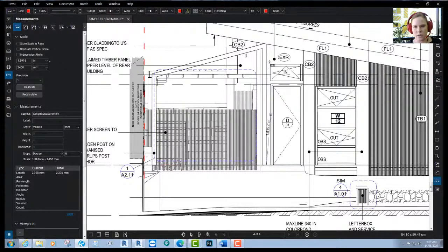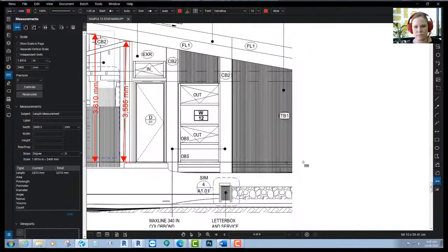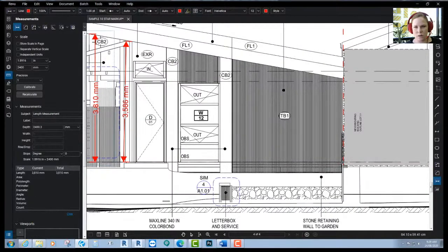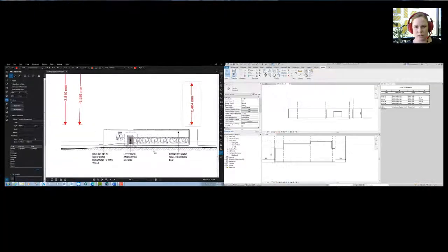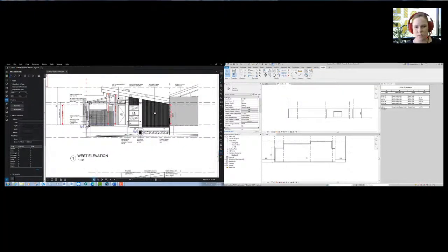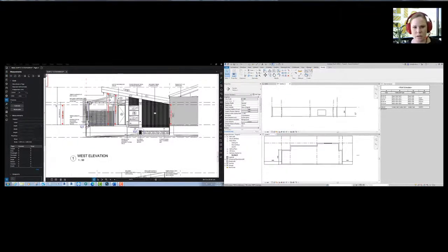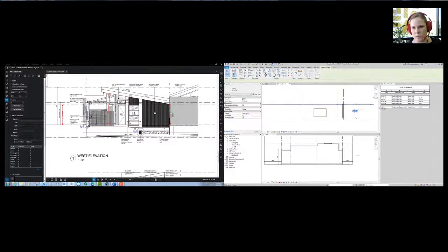And I know there's a corner of the building here. And there. And the boundary one is lower, and we've got a lower ceiling there as well. So I'm now setting up what could be a hand sketch into a Revit model very quickly. So this line that we have here is the level, which basically we had at the ceiling level. So now I've just changed that to what the height of the wall is on the south. I'm just going to draw the other levels in as well so I have them for a later stage.